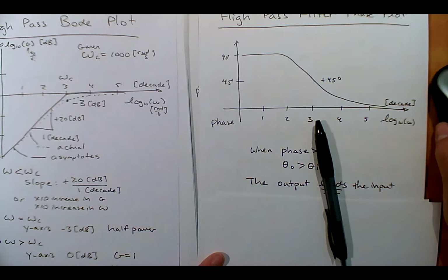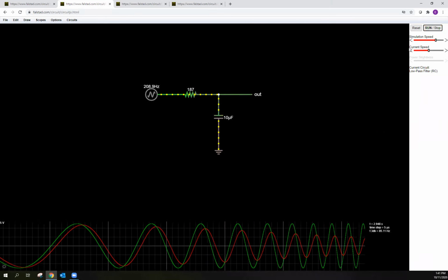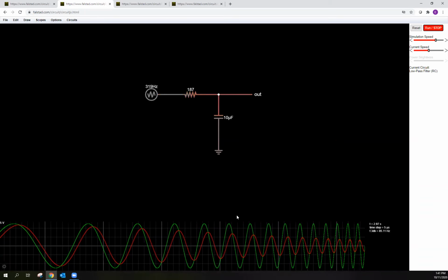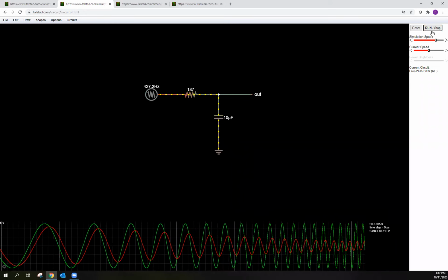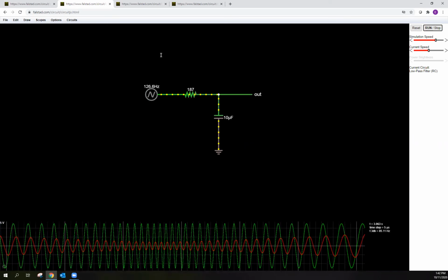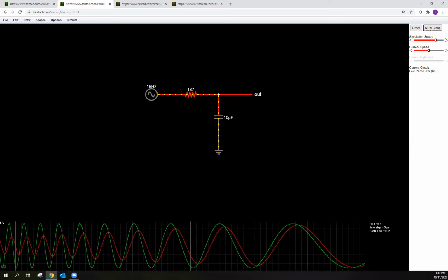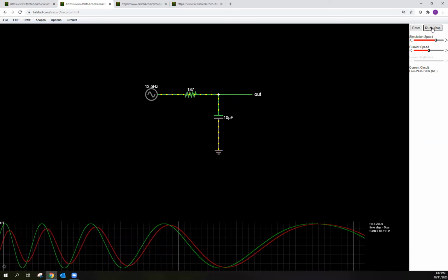So share screen. Okay, so go back to the low pass filter. We're gonna run it again. And look at this, I'm gonna pause it. We're starting to get higher and higher frequencies. This guy is shaking faster and faster, and look what's happening. The output is decreasing in amplitude, and notice relative to one cycle, it's shifting over by 90 degrees, phase lagging, right? And if we keep it going and we go back and slow it down more and more, as this input, VI, slows down more and more, what you see is that the phase of the output gets closer.